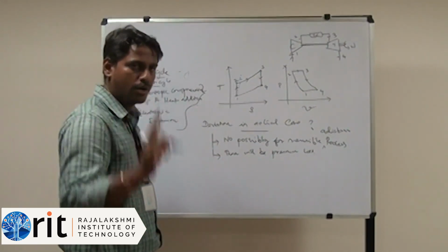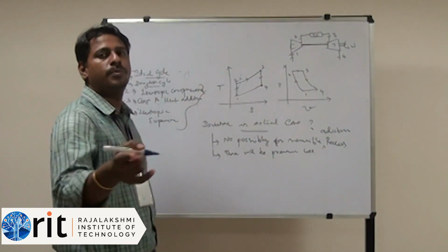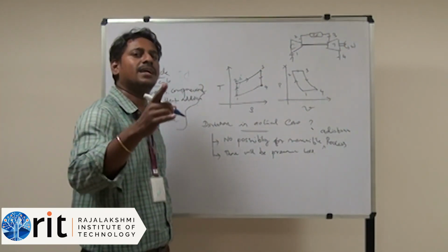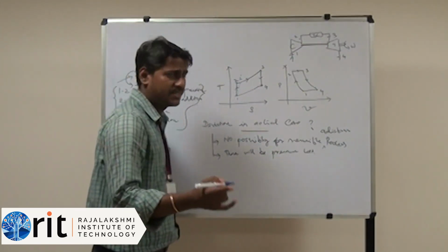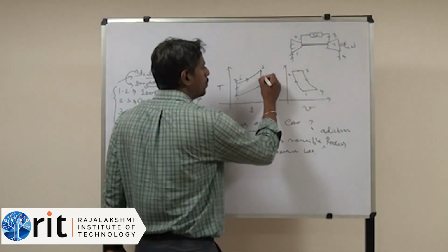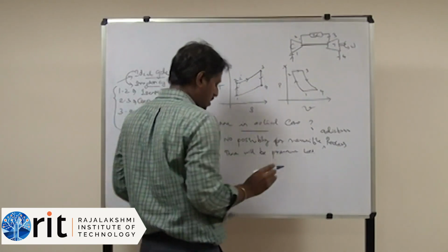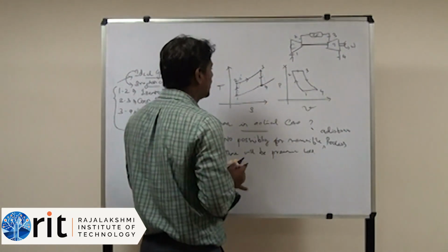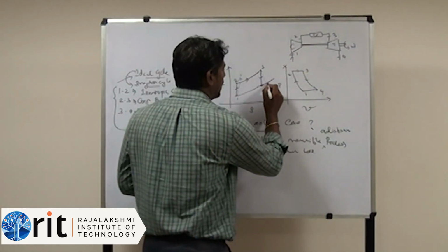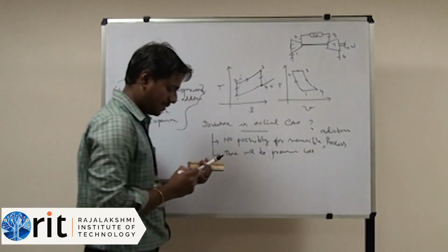Similarly, there will not be the presence of an isentropic expansion process. There is no reversible adiabatic expansion process. What happens is there will be some deviation. So I am representing this using the dotted lines in blue color. I am denoting this point as 4 dash. So this is the case.